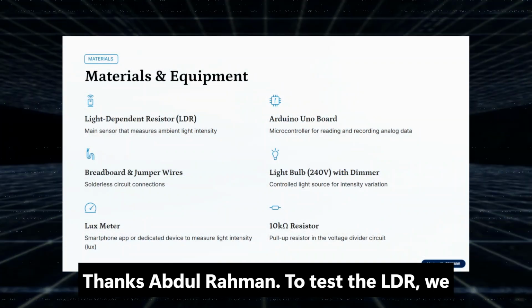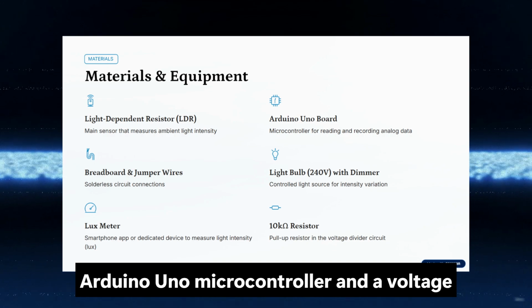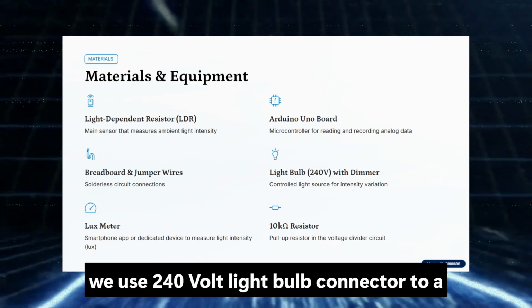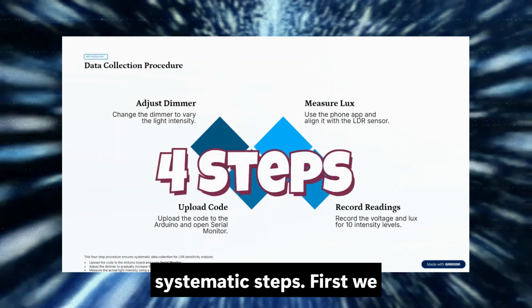Thanks, Abdulrahman. To test the LDR, we built a data collection system using an Arduino Uno microcontroller and a voltage divider circuit featuring a 10 kΩ pull-up resistor. For our control light source, we used a 240-volt light bulb connected to a dimmer. Our methodology involved 4 systematic steps.